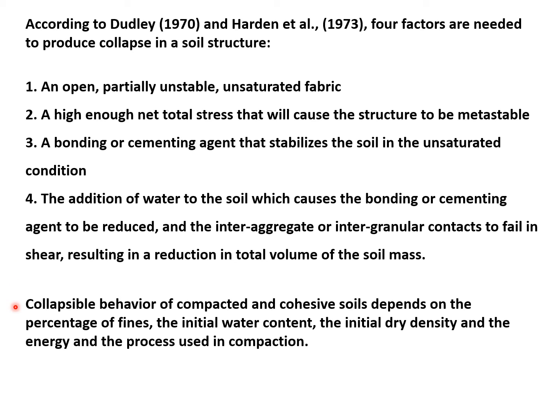So collapsible behavior of compacted and cohesive soils depends on the percentage of fines, the initial water content, the initial dry density, and the energy and the process used in compaction. So these are the different factors which should be considered for the collapsible soils.